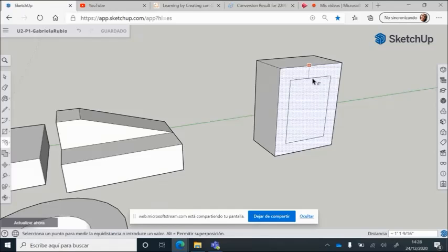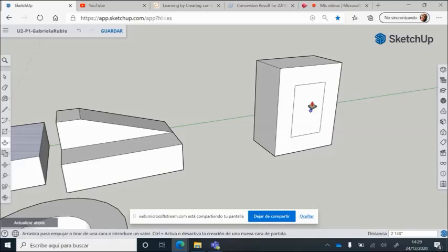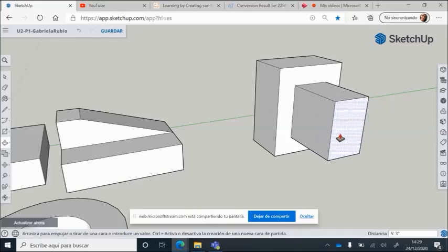As you see, the distance is changing here on the bottom on the coordinates square, but here we can select, for example, a 20 offset distance, and we would have a new square, or a new surface and a new group of edges we can work on as entities. So we can come back to extrusion, and we can extrude this new face we've created a certain distance, for example, let's say 20.